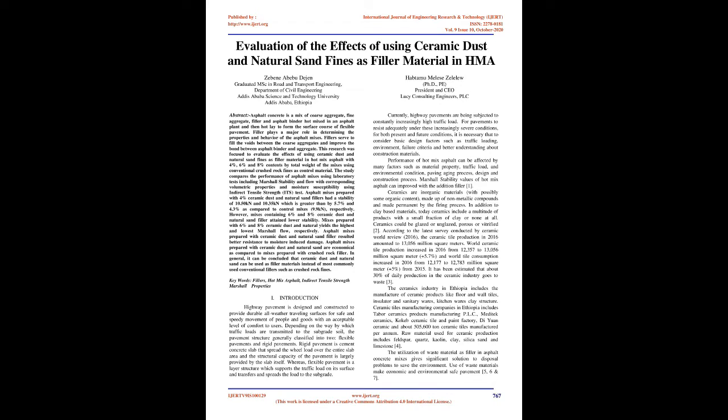This research was focused to evaluate the effects of using ceramic dust and natural sand fines as filler material in hot mix asphalt with 4%, 6%, and 8% contents by total weight of the mixes, using conventional crushed rock fines as control material. The study compares the performance of asphalt mixes using laboratory tests including Marshall stability and flow with corresponding volumetric properties, and moisture susceptibility using the indirect tensile strength, ITS, test.